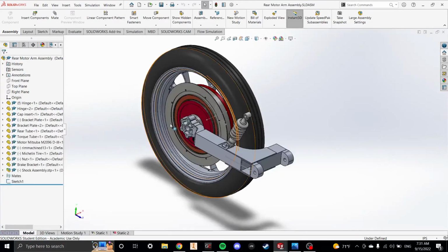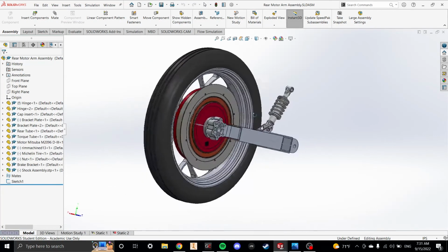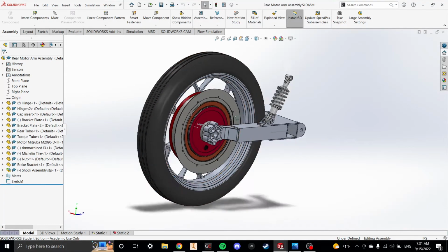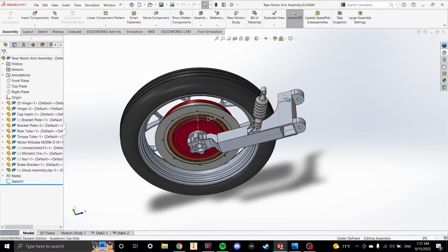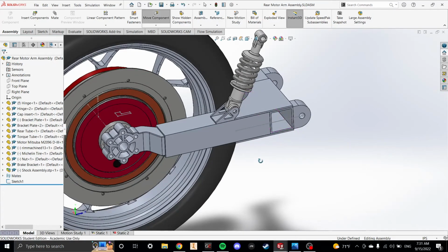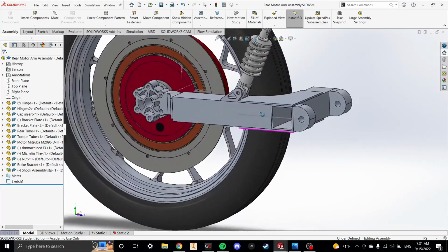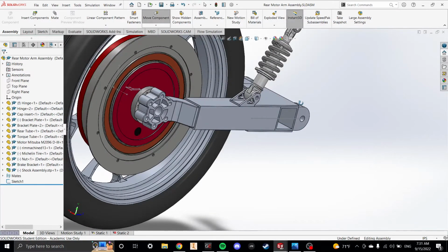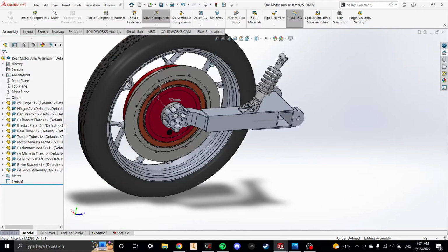But it was the rear suspension. You kind of see it here. We have the motor here, we have the wheel, the tire on top, and then this whole assembly here. This is an interesting design because we wanted to make this as light as possible. Our previous year's suspension was quite heavy, and so we've done it out of an assembly this year with tubes, gussets, and then a big insert at the top for our motor.